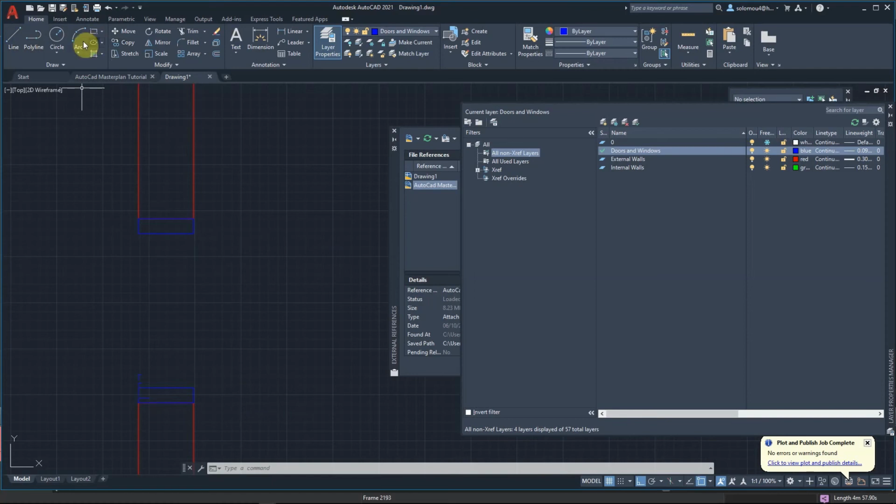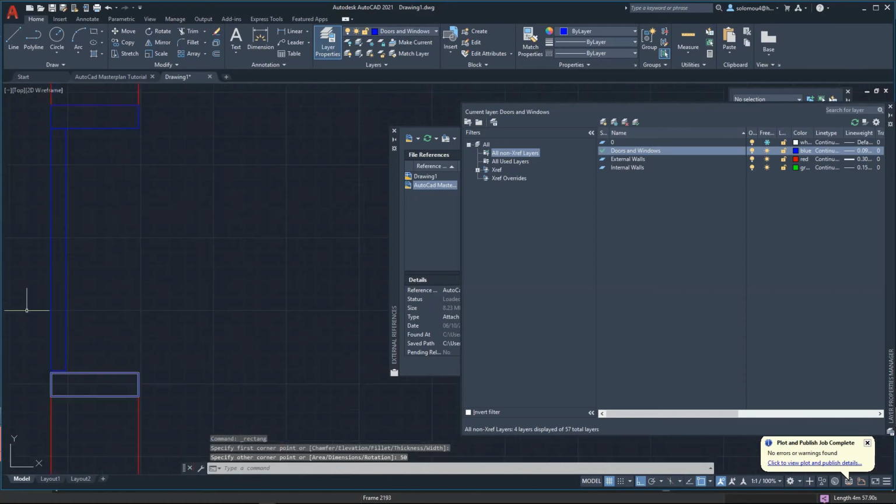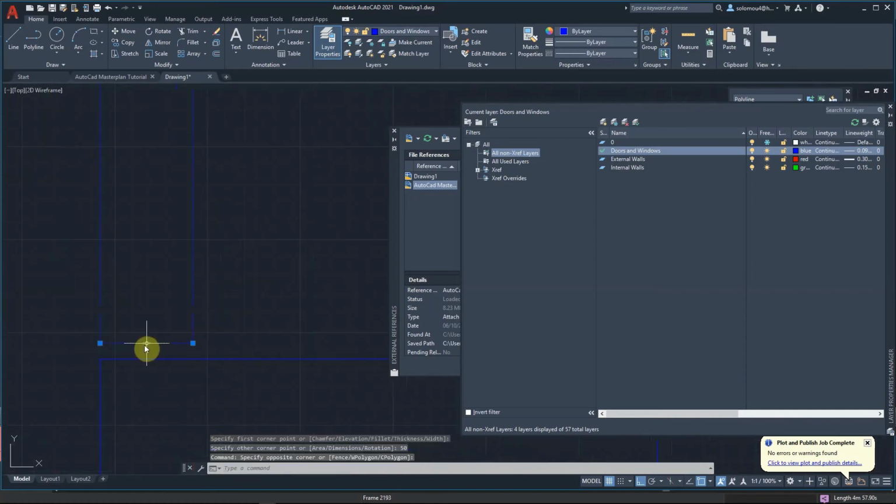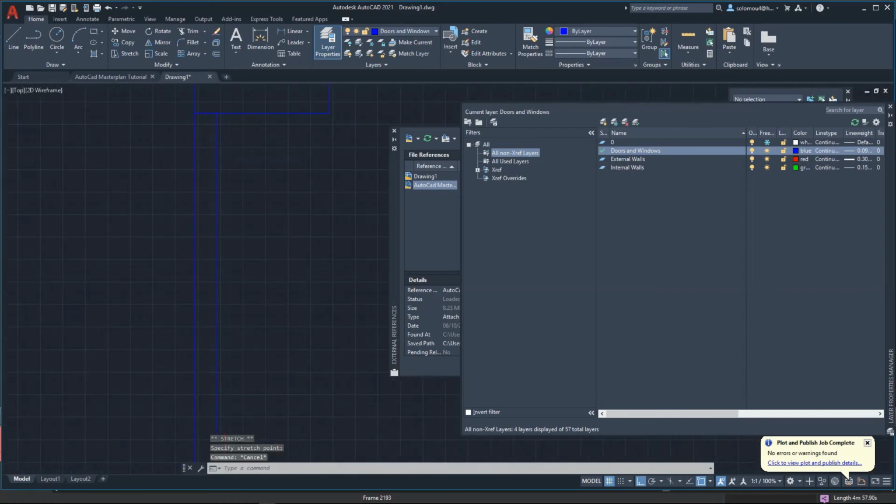So in order to create the door is another polyline, or we can actually use the create the rectangle line, which is here. And we'll start from this side, and we'll go all the way down here and drag it across by 50 and press enter. There we go. Oh, it's not quite matching. We didn't quite go all the way. It's fine. We select this, we left click on that, and we drag it all the way down. Perfect.